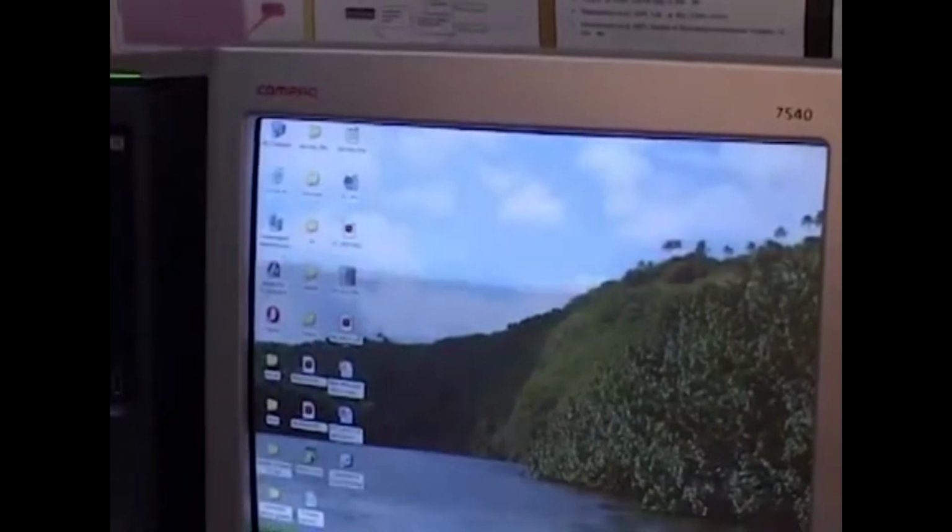So we have a licensed version of the software called Image Pro, which is used to identify the signal responses from the CCD camera, and essentially I am just in about a few minutes going to demonstrate how we can read out using the eyepiece and how we can see here. Now the advantage that this software also offers is that we do have a scaling mechanism here, where by feeding the particular scale factor, the magnification factor, we are able to generate a cursor which can give you dimensions as you join different points on the same image.